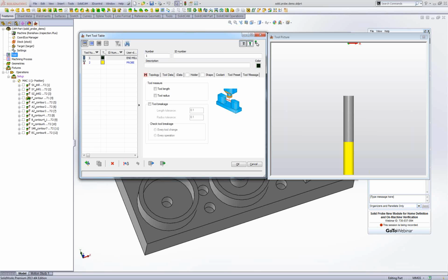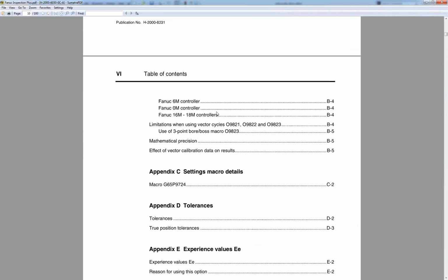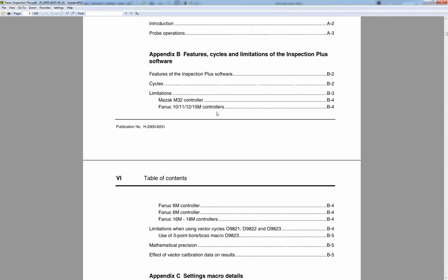You know, as I say, if we take the Fanuc example, the Renishaw, they have the Inspection Plus software. If you go to a customer's machine and he has Inspection Plus cycles, you can use this file. If he has another package different from Inspection Plus, there are many packages on the market today, you need to write this include file to adapt to the cycles that you find at this customer. The posts depend on the cycles the customer has.